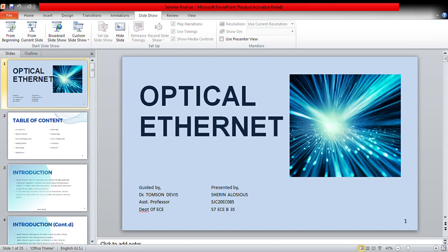Passive optical Ethernet is an emerging local subscriber access architecture that combines low-cost point-to-point fiber infrastructure with Ethernet. EPONs, that means Ethernet passive optical networks, are designed to carry Ethernet frames. Data is transmitted to the destination in frames at standard rates, and utilizes a single trunk fiber that extends from the central office to a passive optical splitter, which then connects to multiple optical drop fibers connected to the subscriber nodes.